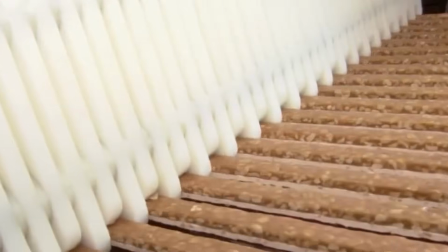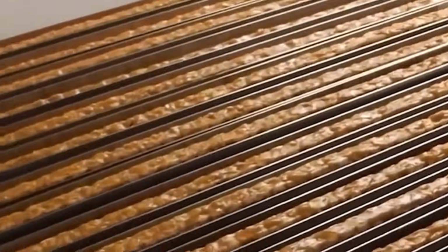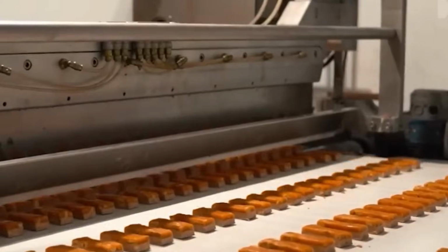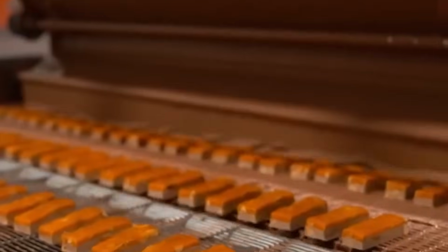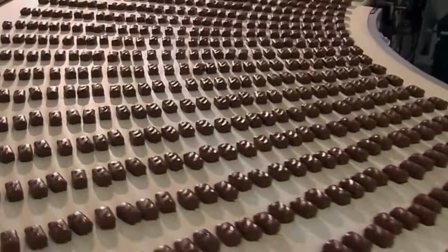The result is a light, aerated nougat with controlled density between 0.35 and 0.45 g/cm3. The nougat is extruded through a calibrated nozzle system onto a continuously moving cooling belt lined with a polyethylene release film. The nougat band is cooled to below 20 degrees C using overhead chillers and bottom surface cold plates. Once cooled, a uniform layer of peanut butter is deposited onto the surface using a curtain depositor. The thickness of this layer is maintained using servo-controlled doctor blades.